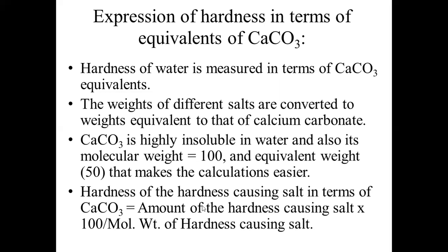Now we are able to see here the hardness of the hardness causing salt in terms of calcium carbonate is equal to amount of the hardness causing salt into 100 divided by molecular weight of the hardness causing salt.